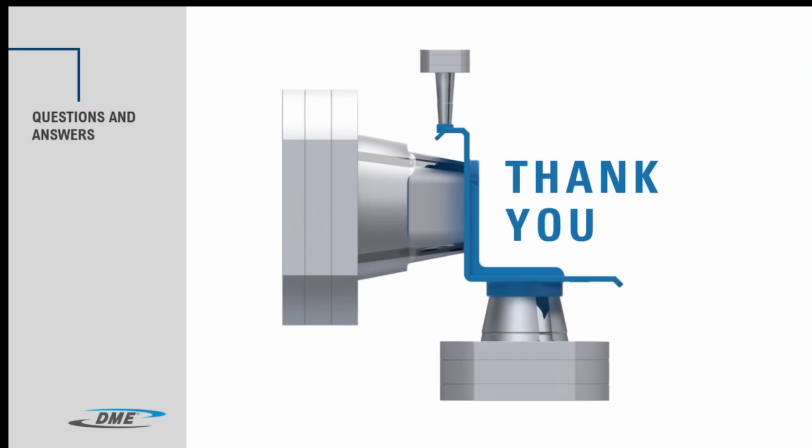Thank you. Now I'm going to read some other questions, from Paul. Can S-core or DuraCore be integrated into existing mold designs, or are they mainly suited for new tool builds? With a minor modification on the mold base, we can incorporate both DuraCore and S-core. A slight retrofitting is required.